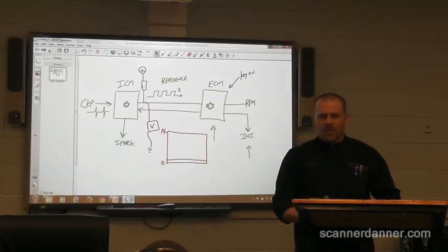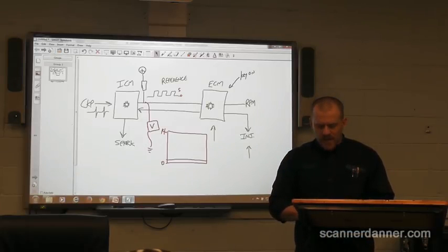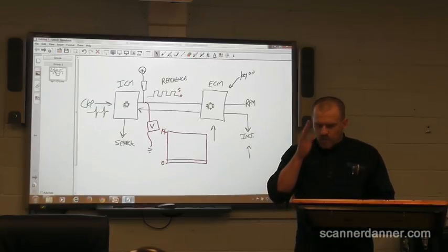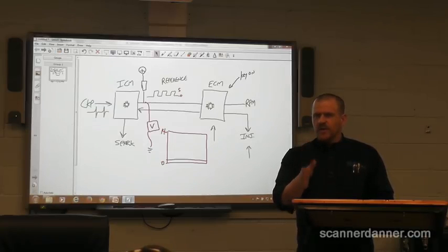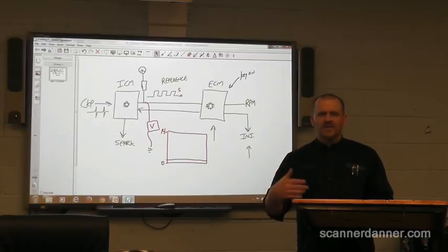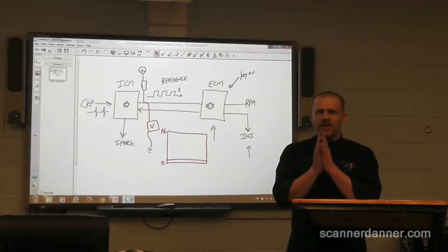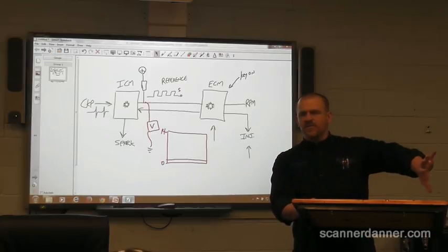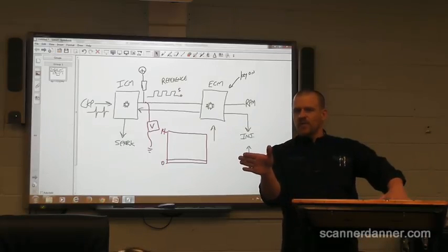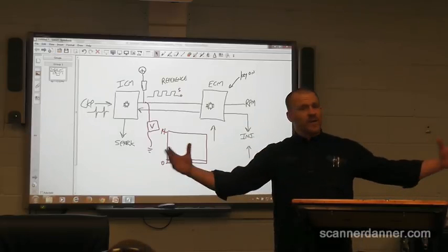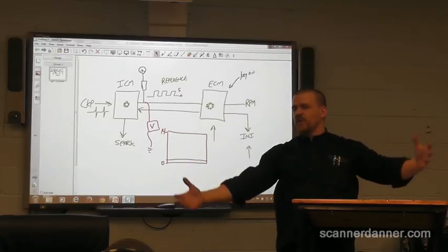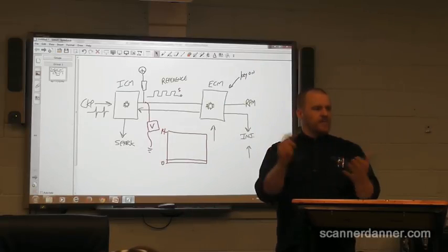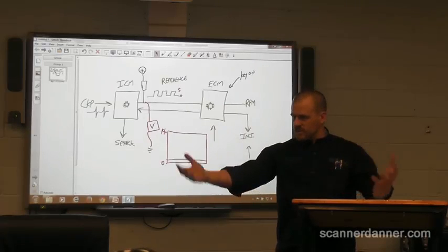Let me back up. When we're troubleshooting and we're trying to find direction, we're always looking for tests that say, I'm going to turn left or right. And I've started using this in an analogy the past couple of years, and I think it works really well. I'm always looking for something that I can eliminate this bunch of variables, and then I'll walk down this road, which narrows the possibilities. Because right now, we have this whole mess of things it could be. Crank sensor, module, wiring, computer, injectors, fuses, and so on.